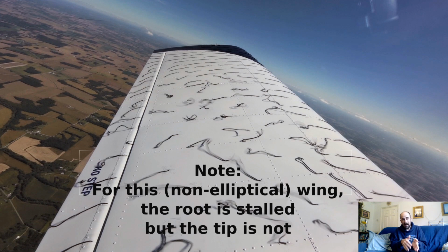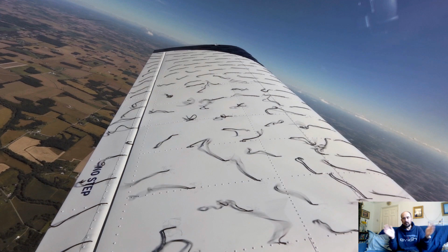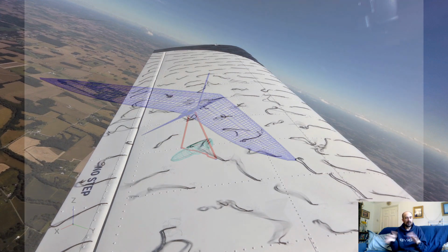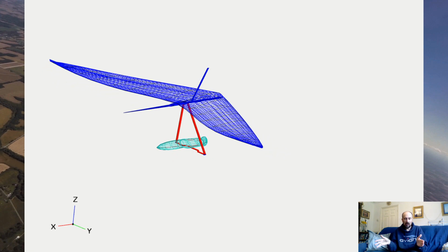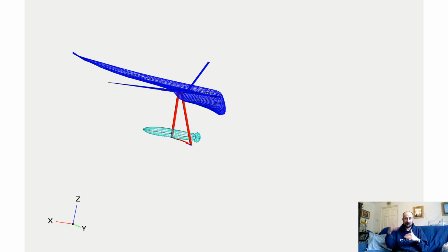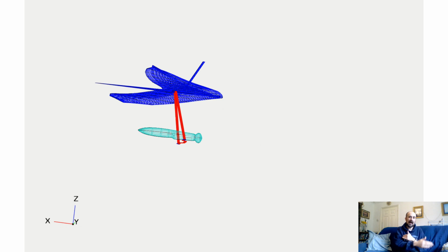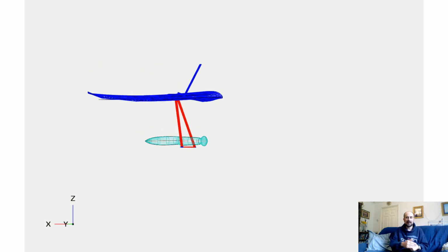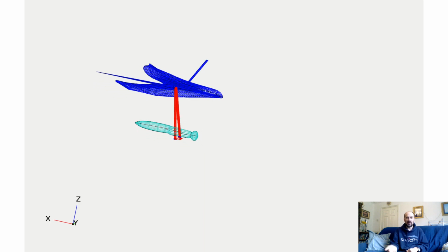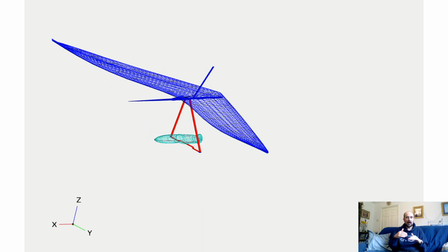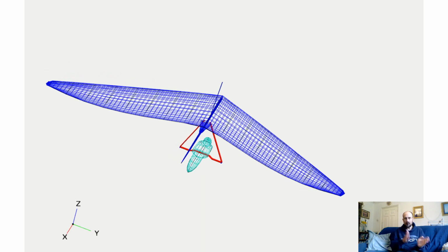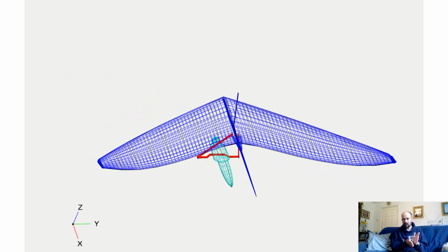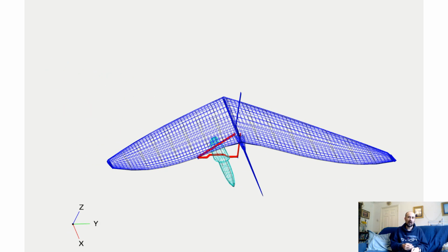The other thing from our point of view is that if you have that elliptical shaped wing and you have no twist at all, then you can't achieve pitch stability for a flying wing. So if you're trying to have a flying wing which also has an elliptical lift distribution, you actually can do that, but it has to be achieved partly through twist. So then that does mean that you're only able to get that perfect lift distribution for a single design point.